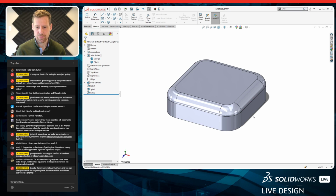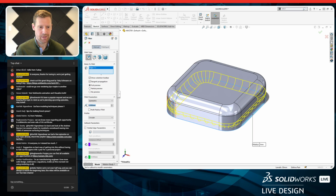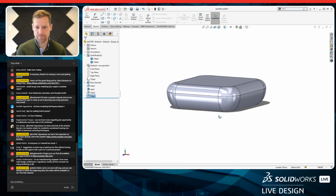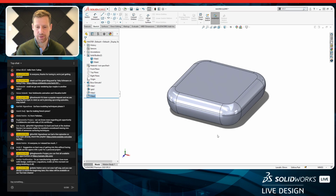Okay, let's finish this off by adding a fillet here to the bottom face. Again, I don't want this to be symmetric, so under fillet parameters, we'll choose asymmetric. And then here I'm going to use my Alt key to increase or decrease this until I get something that I like. So let's say about right there looks good. So we'll say a 7 millimeter fillet in that direction, 10 millimeter in the other. And that looks about right, I think.